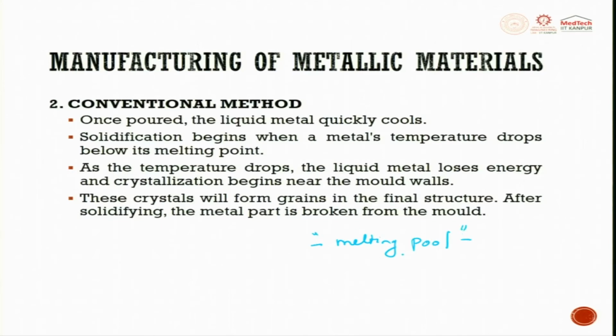This melt pool analogy, you should try to take everything from casting and bring it here. Melt pool is an area where the metal melts and then it forms a pool. So, this one is very important. When you move the laser in this direction, the melt pool also does it. You can have a backward trend, or you can also have a forward trend. The laser moves ahead and the melt pool is created. So, you can create in any direction depending upon your requirement.